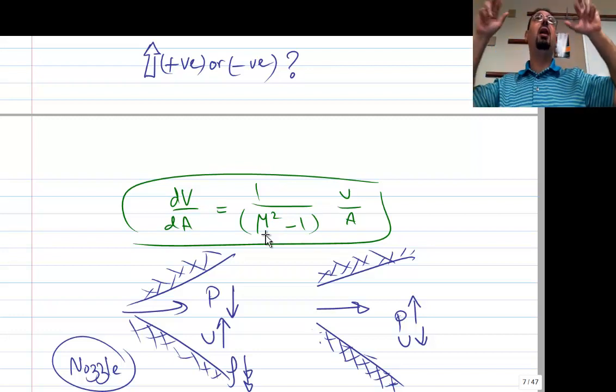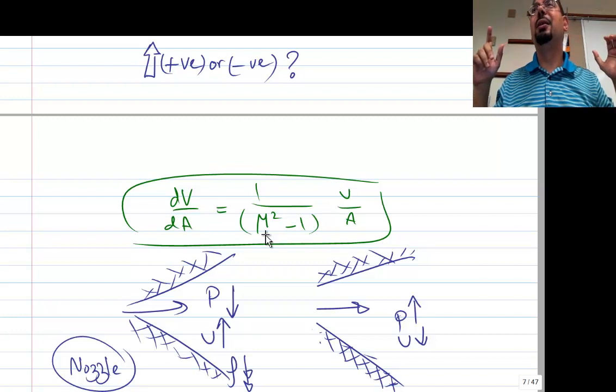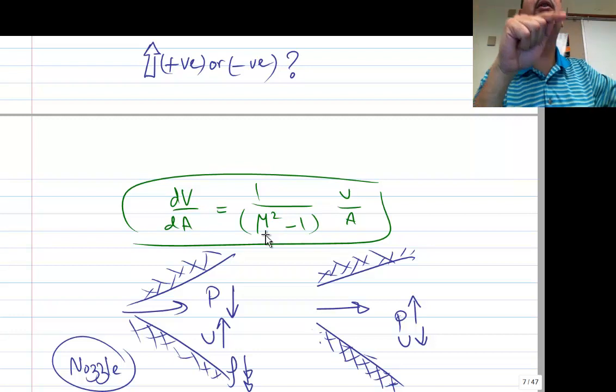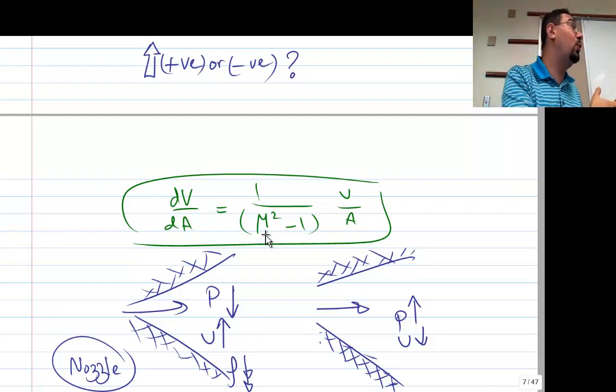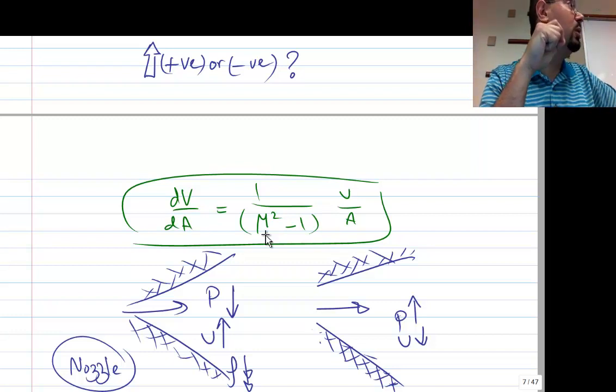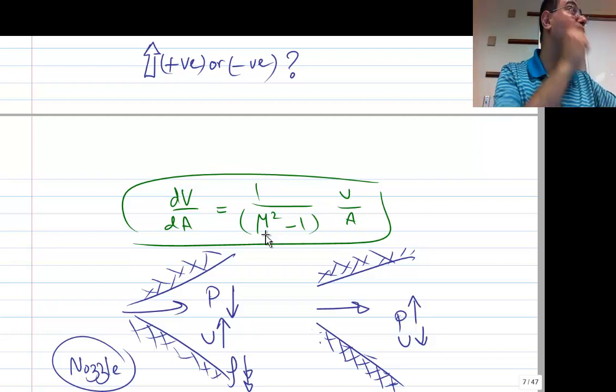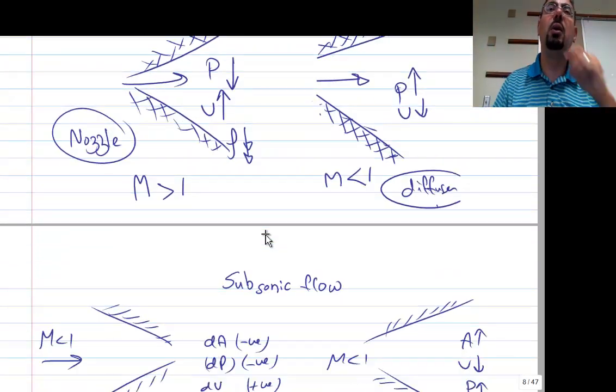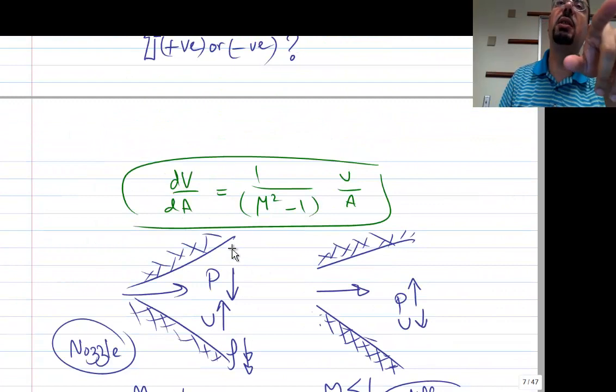Almost solid, almost incompressible. So basically when M goes to 0, that's incompressible flow. So all this analysis in fluid 1 was the limit when M goes to 0. All the solutions that we have will turn into basically the equations in fluid 1 when M goes to 0. So incompressible flow is the limit for very large acoustic speed, or basically almost incompressible flow. Alright? So that's easy to answer, right?